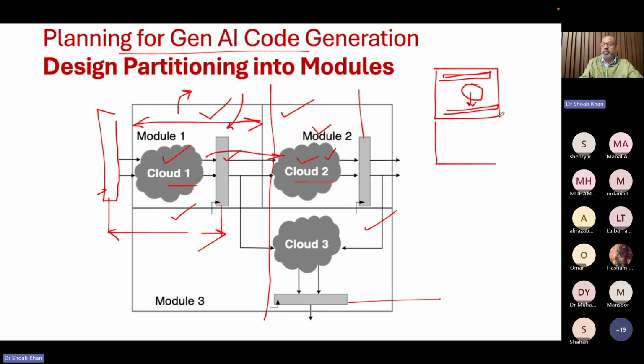So if you want to really make them pipelined, to have many of the iterations, let's say all the 32-bit iterations, you unroll them. So you are going to basically replicate this logic 32 times.